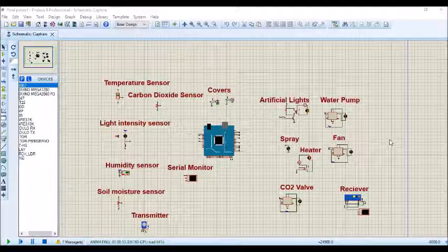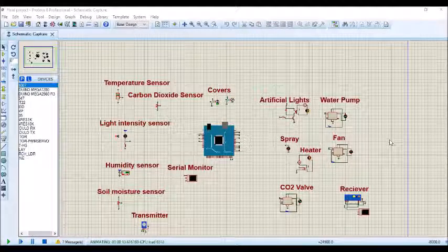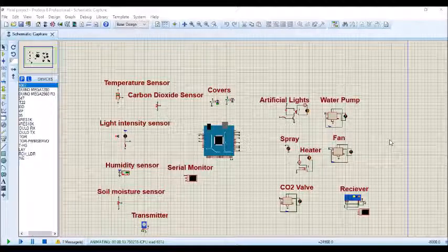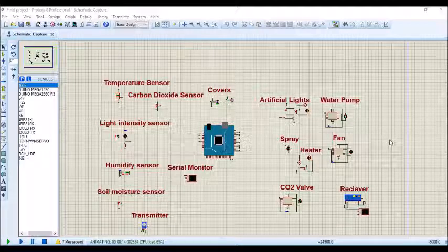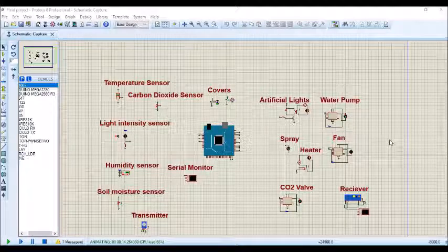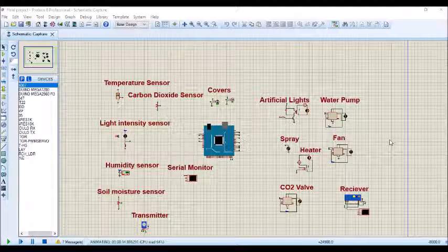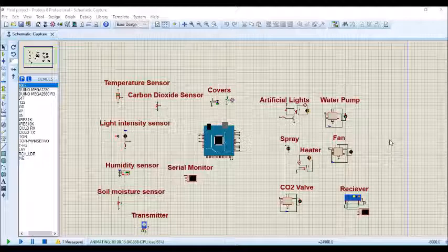The inputs obtained from the analog sensor are captured by Arduino. When the sensor does not sense moisture in the soil, the water pump is turned on until it reaches the required level. The carbon dioxide level is controlled by CO2 valves. The sensor is coded according to the changes in voltage level, which in turn changes the concentration. The level of concentration controls the CO2 valve.